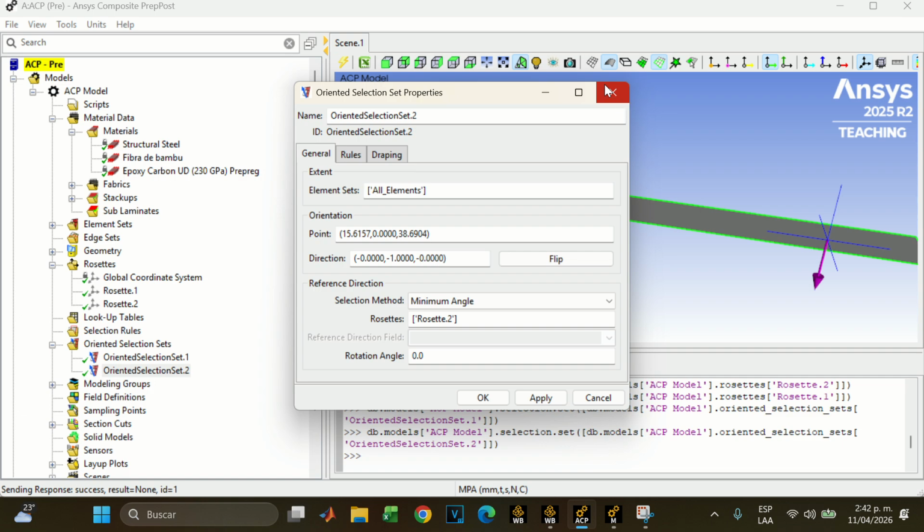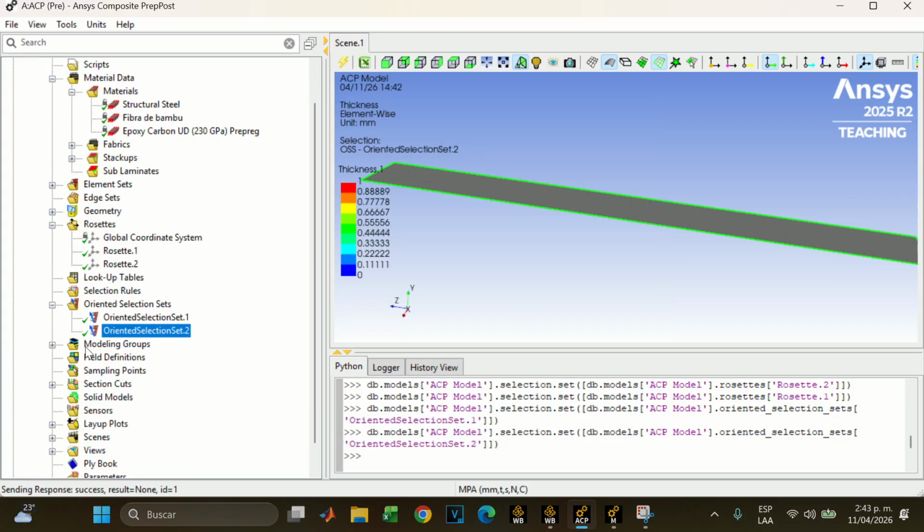And the physical phenomenon when we apply the load, because ANSYS is blind in that regard. It's not going to differentiate if we are applying the tensile load, and it's not going to do it in a uniform way. It's just going to test it out, assuming that the material is fixed from one of the points, but if the other is not fixed, it's just going to continue on and it can rotate and translate around itself. So this is why we have to avoid that, and we just want a straight fiber movement, right? So this is what we are planning.